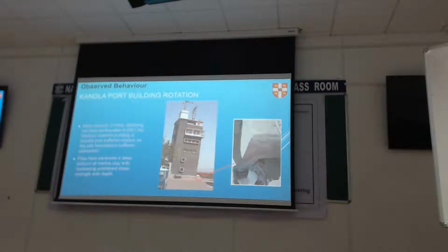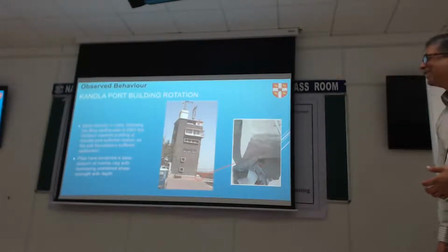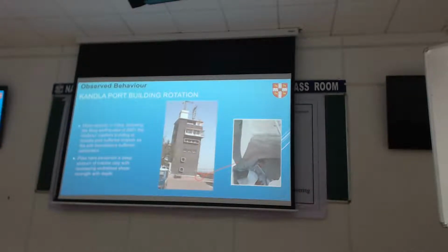If I show you the corner of that, they exposed the pile, and you can see the pile has actually punched in. There's also a lot of rubbish dumped into a newly dug hole: newspapers, plastic papers, and all that. But ignoring all that, it certainly was a problem.